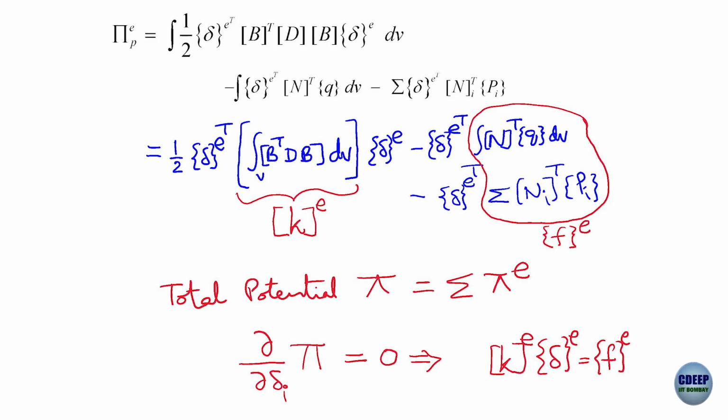The nodal displacements. Earlier when we solved the problems, it was C0, C1, C2, C3, etc. Now it has become nodal displacements. Over a domain, over an element, how can I get different displacements and different strain energies, different work potentials, because within the element, how displacement varies, I have already fixed, it is a linear variation.